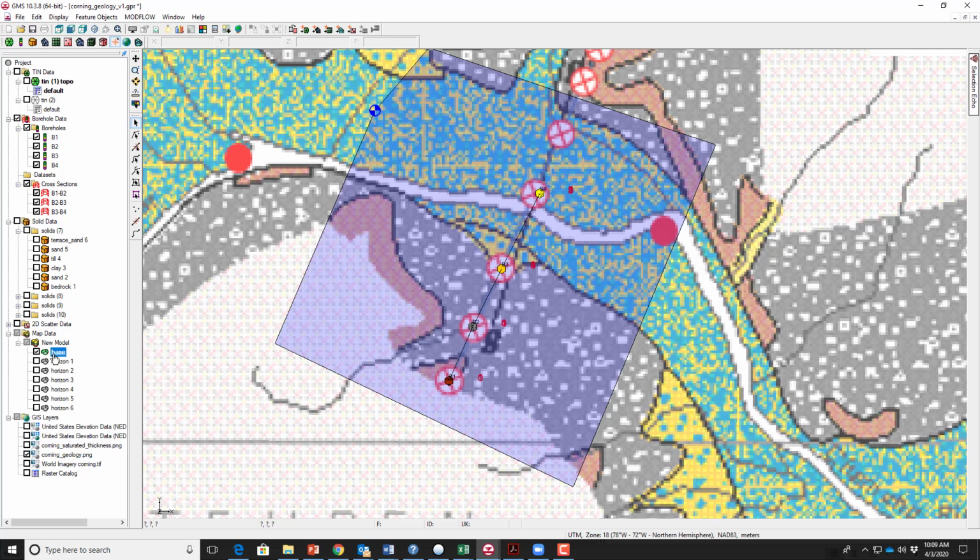And before I started with that, actually, when I did the base coverage, I went and set this up. So I did redistribute vertices. Well, I selected the line and did redistribute vertices, and I made them, I don't know, 20 or 30 meters across.